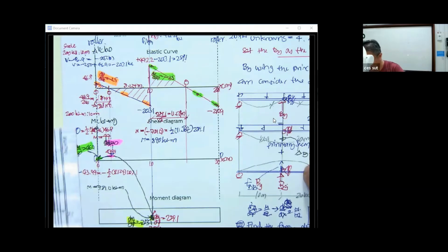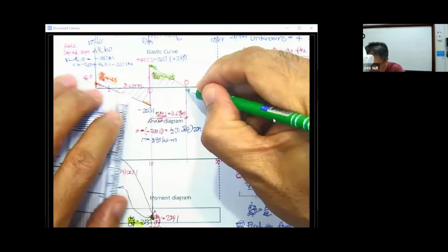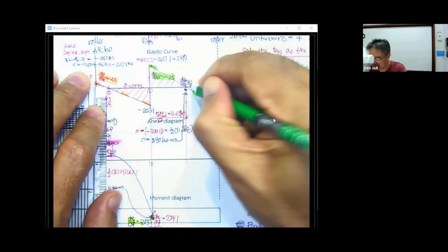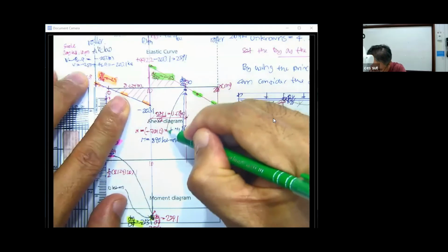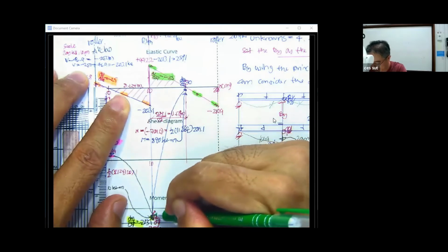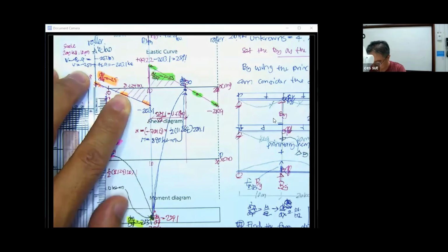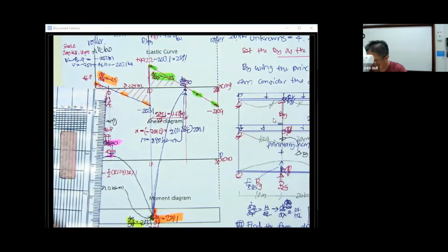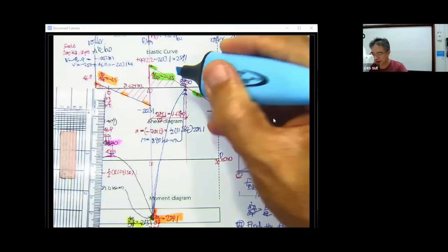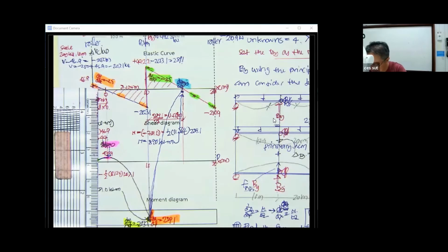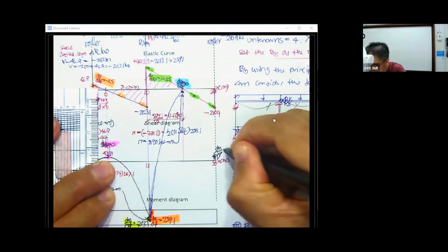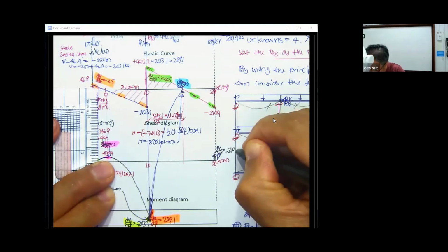That is going to be 4.5, the curve like this. This is going to be the curve like this, and then the dM/dx is going to be 0, and then the curve is going to be something like this. Again, this is your dM/dx. So this is the slope of this, and this is the slope over here. For the last one you can draw the picture easily, because from this point it goes downward. Here the dM/dx is going to equal V here, minus 210.9, and the curve is going to be something like this.